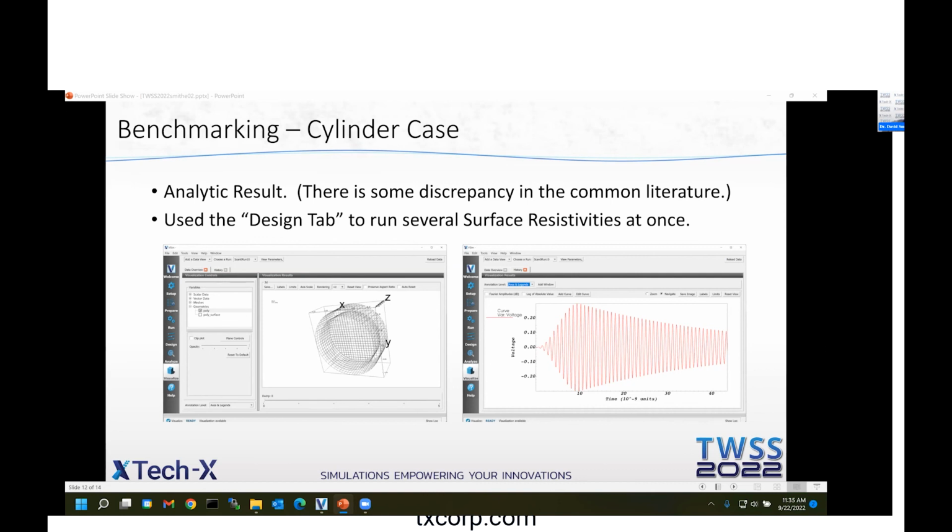Have you performed any grid sensitivity analysis? Yes, in fact, I have. That little 15% discrepancy that's been annoying me. The very first thing I did is double the grid and double it again. And unfortunately, it gives the same answer. So actually, it is quite grid insensitive already at this point, even though it's not the perfect answer yet.